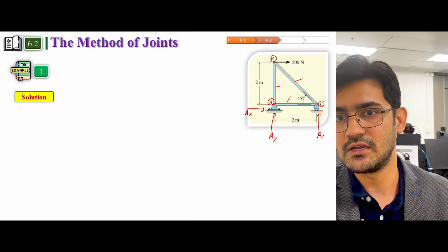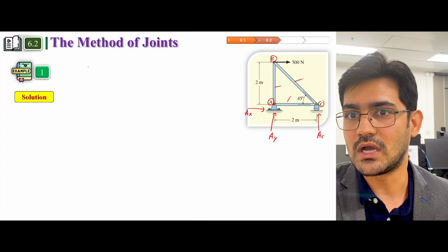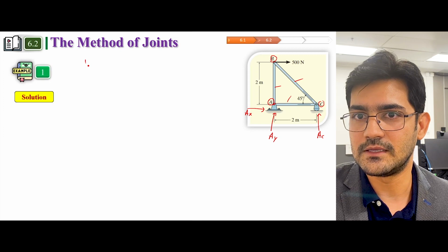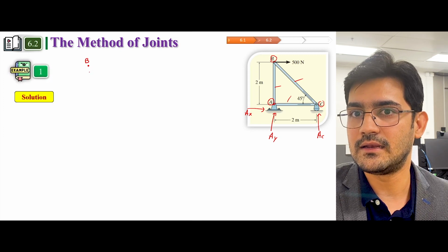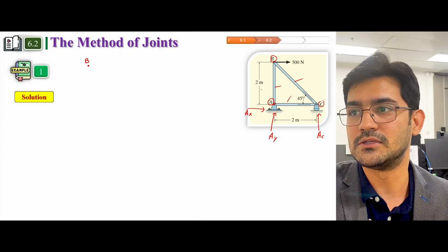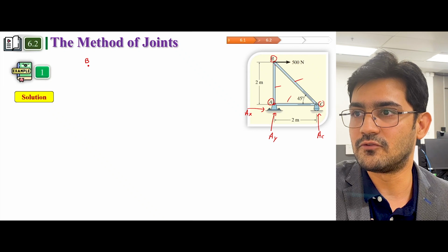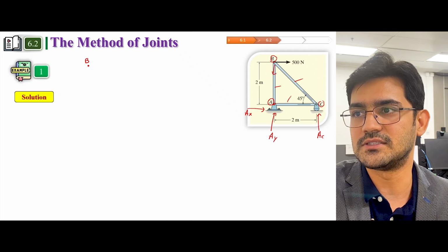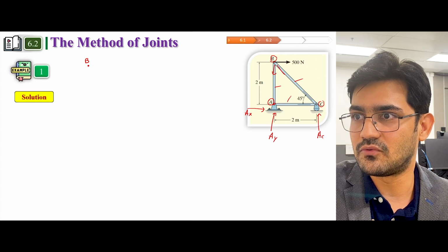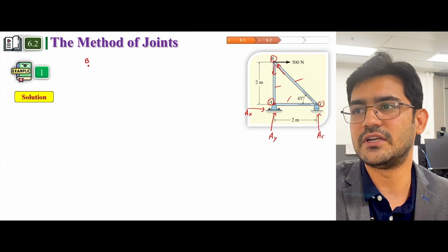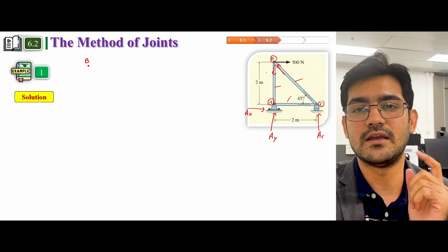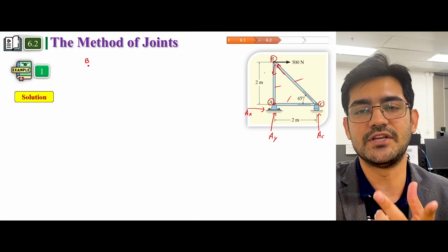So the B looks easier. So we'll try to isolate B. So how we will isolate? We will put this point. This is our point B, and there are two forces acting on that point from these two slender members. So this member is also applying a force. We can assume it as a compression or tension. It depends. So there is another force acting here. So it doesn't really matter which direction you are pointing, you're going to get the result. So if you have directed a wrong direction, then you will get a negative result. So you can change the direction later.